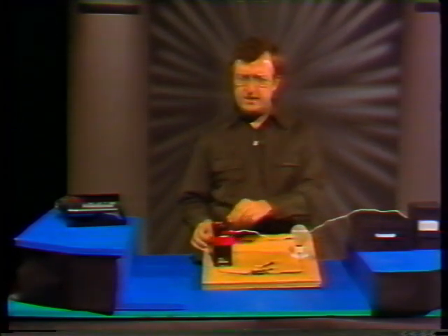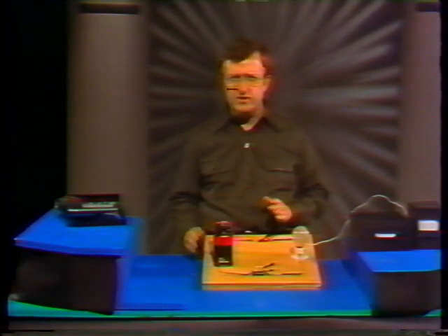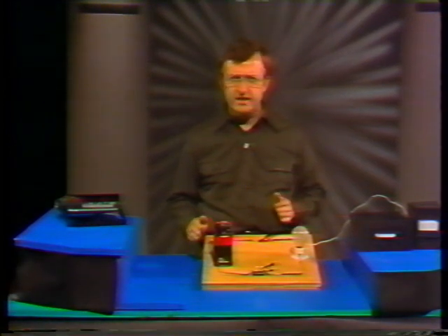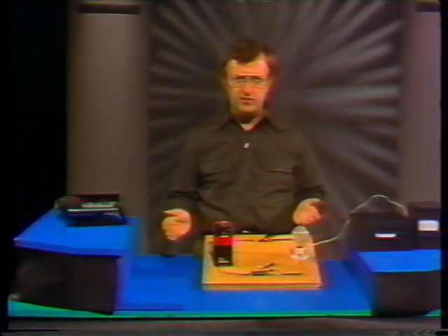Now, the last meter we're going to use can serve several purposes. We have it set so that it functions as an ohm meter to measure resistance. Because we're going to take a resistance measurement, we have to de-energize the circuit and disconnect the component we want to test. If we didn't disconnect the component, 2 things could happen. At worst, we'd stand a good chance of damaging the meter, and at best, we'd get an inaccurate reading because the meter might pick up resistance from other components.